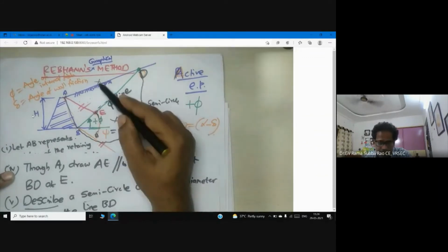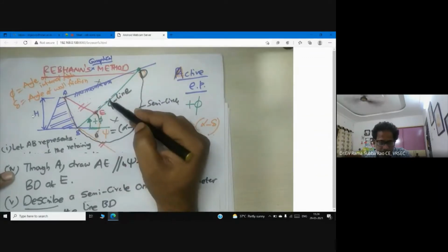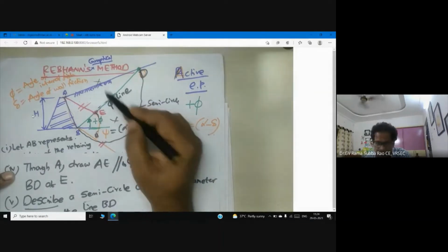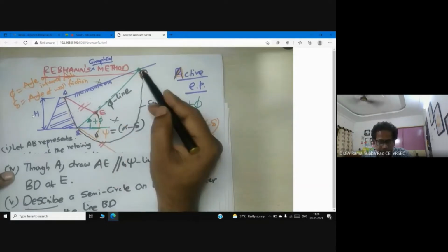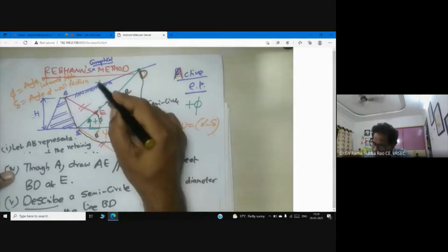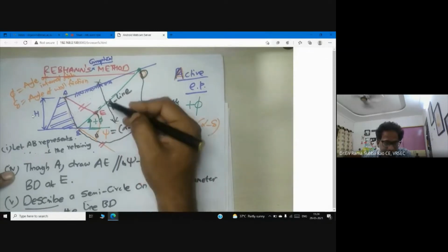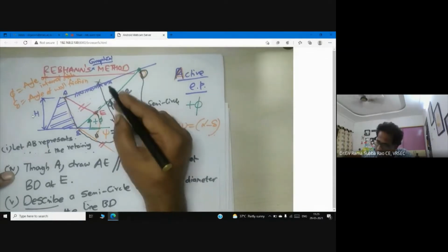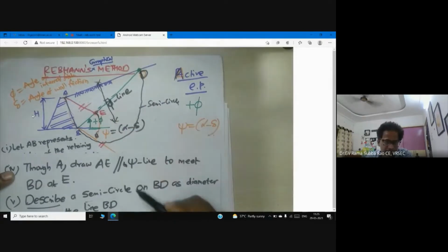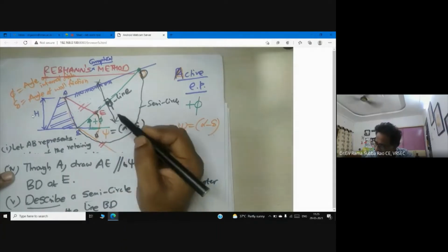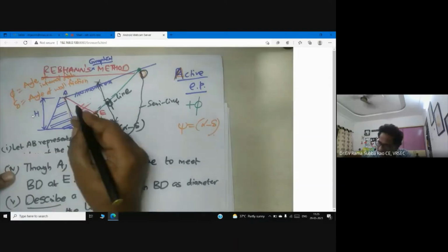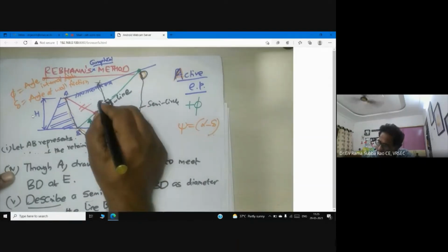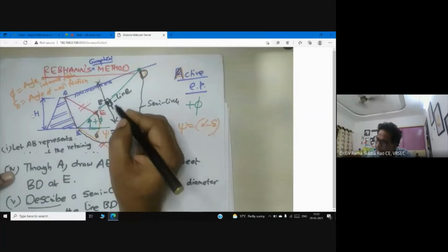So you need to take a measurement more than half the length. Then you draw the arc on top and bottom with B at center, and again D at center. Draw the arc with same length. Then you can bisect the line. Probably you can recollect your days of engineering graphics. Okay, now you see, because we are discussing graphical method. Now you see, I have this point. Can anyone tell me what is this point now? So this point is undoubtedly E. This point is E.